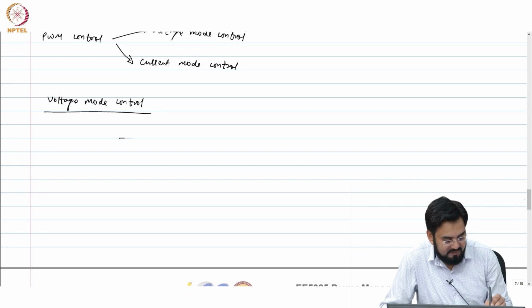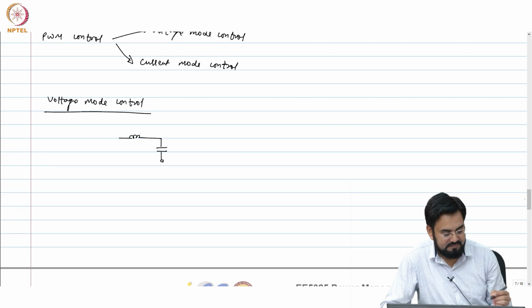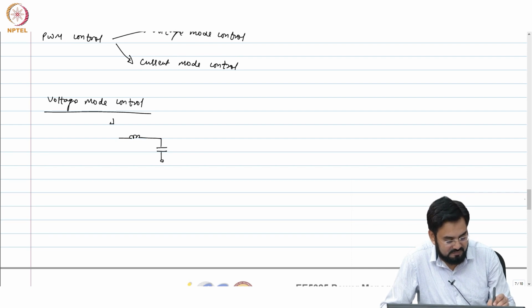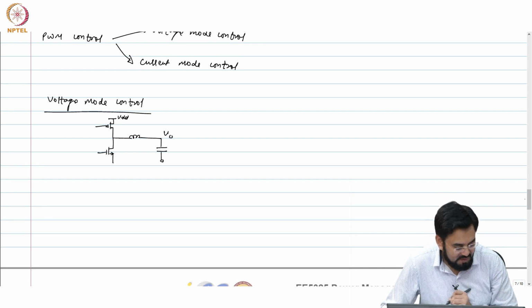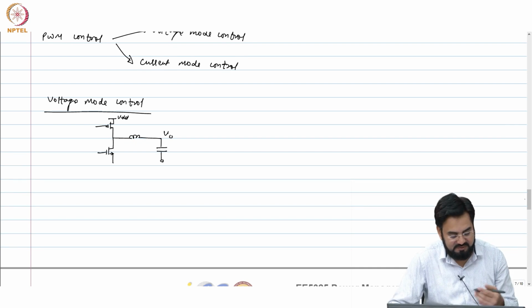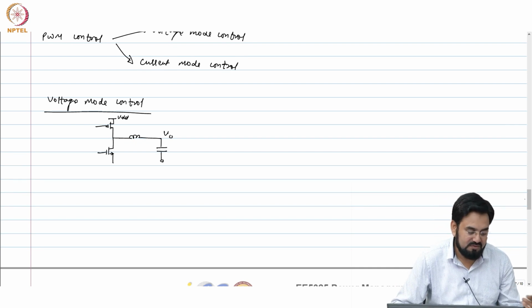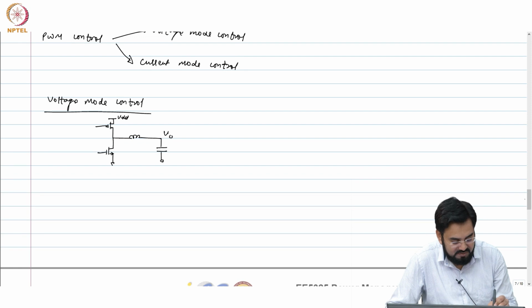So, what you have is your L, C, so usually that is how you implement your switches. You can use bipolar also, but since we use MOSFET technology, we just use MOS. So, for the high side you use PMOS, for the low side you use NMOS, and these MOSFETs are quite big.